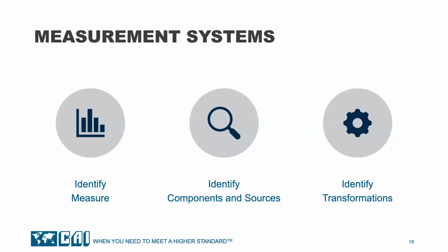Advanced analytics form a part of our overall measurement system. What exactly do we want to measure? If we have a document management system, we may want to measure how long it takes to review a document, how many review cycles a document has had, how long it takes to approve the average document. If we are constructing a maintenance and reliability system, we may want to capture how many times a valve has been cycled on and off, how many hours are on a pump, or the flow rates across an RO membrane before and after sanitization to determine the effectiveness of a sanitization cycle.